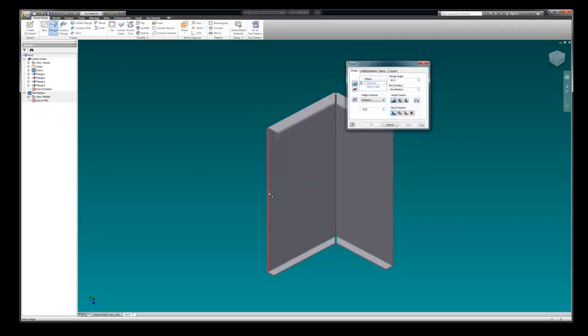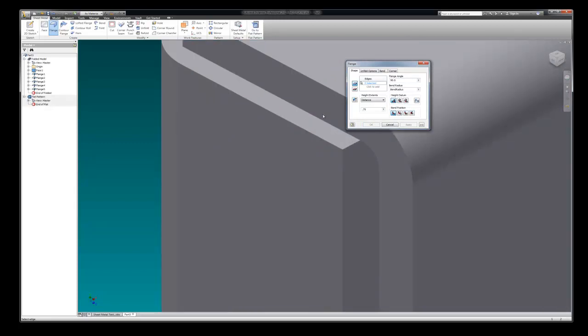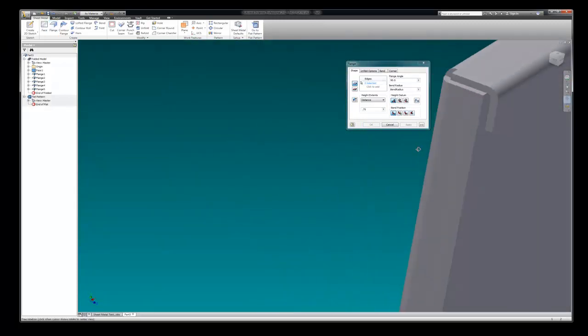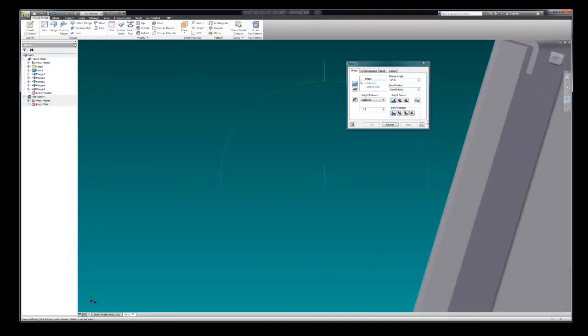Okay. And then we got this one over on this side here, so we got a flange coming up there. Now this is pretty cool what this does. So I'm going to pick it, and your flange there is 3/4. I think I already have 3/4 in here, so if I go on this drop down arrow, I can just pick it and go apply. Now look what it does. It sets it back inside and gives us that clearance that we need.